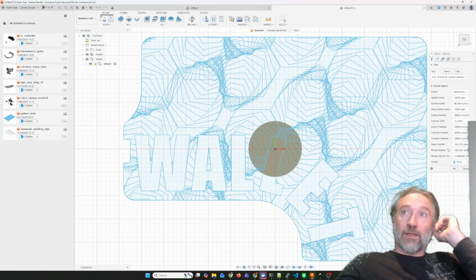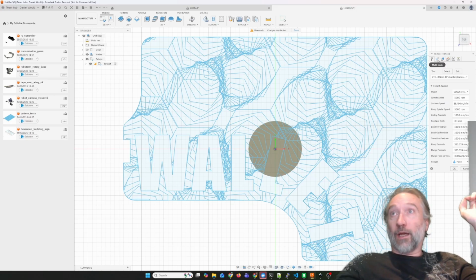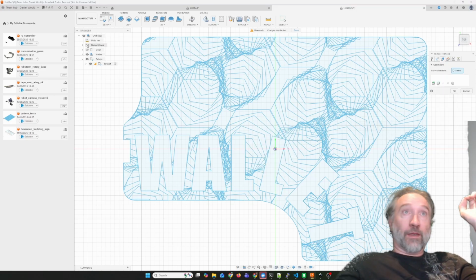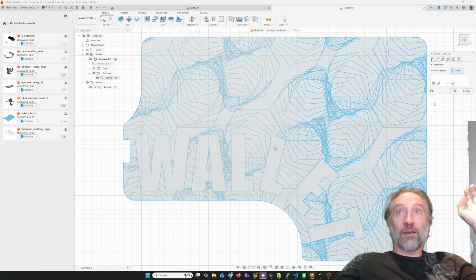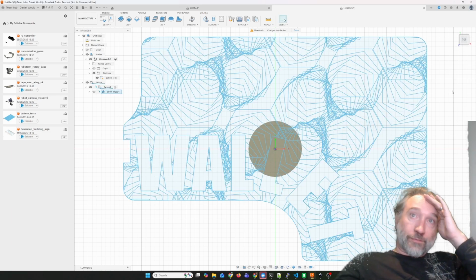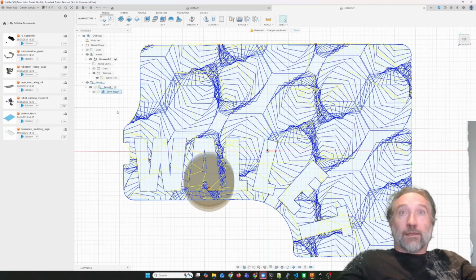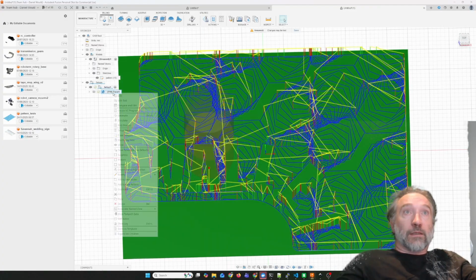I'm not going to worry about any of these spindle speeds, because when I run the engraving bit, I just turn the spindle on, and when I run it on the laser, then the laser does it. Geometry, I like to select from here. It depends on if you've got more stuff, but since I want the whole pattern, I don't want to select all the lines individually. I want to do that. Hit go. Alrighty. So Fusion has sat and thought about it, and it has created a plan.